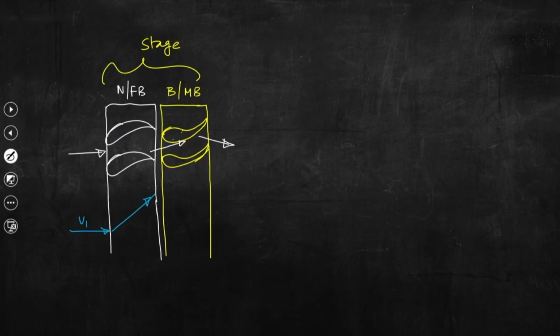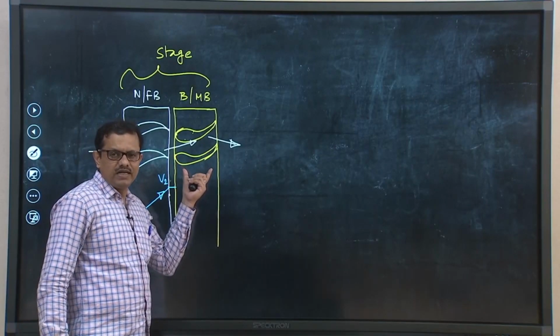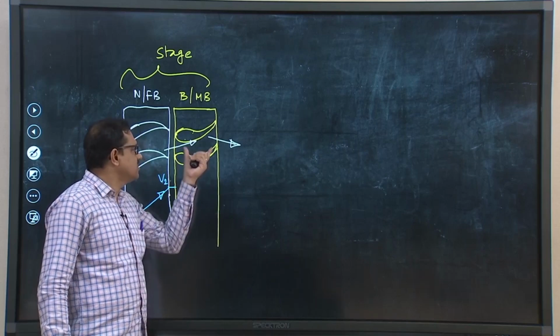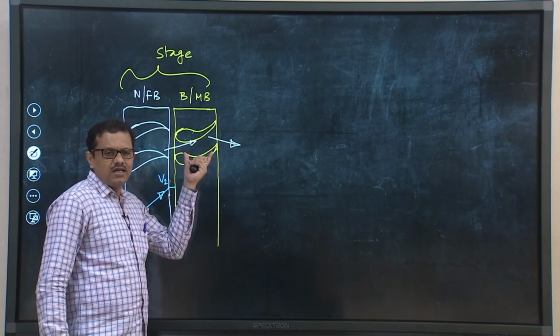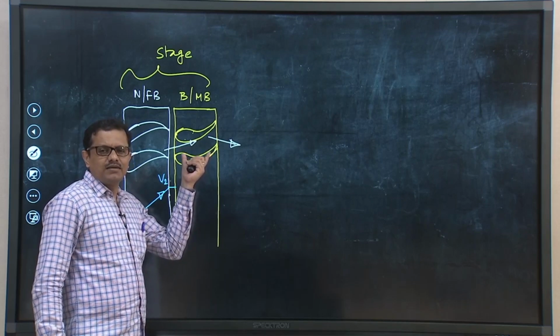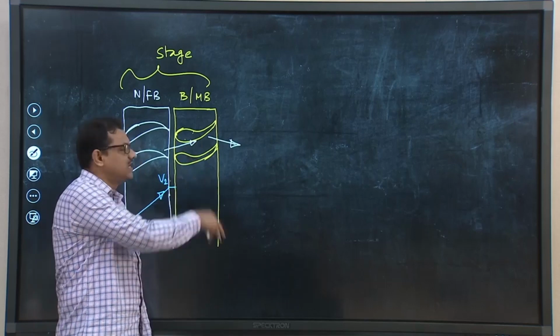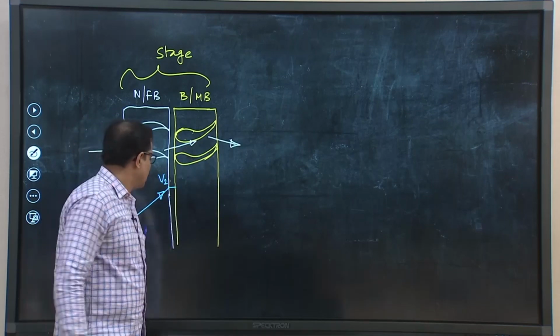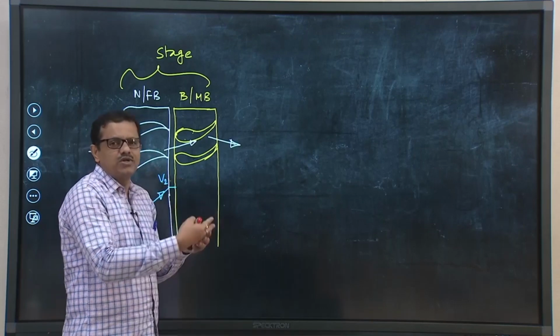So, this is V2, and basically this is the first row of blades or moving blades. So, while steam is passing through the blade passage, the kinetic energy would be absorbed by the moving blades rows. Now, that kinetic energy would be utilized to produce torque.